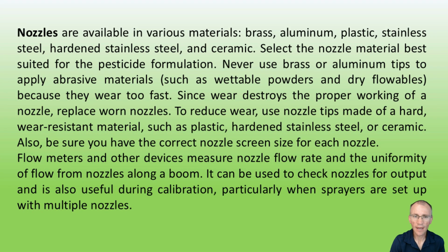Now there's going to be a lot of choices with nozzles. Nozzles are available in various materials: brass, aluminum, plastic, stainless steel, hardened stainless steel, and ceramic. Select the nozzle material best suited for the pesticide formulation. Never use brass or aluminum tips to apply abrasive materials such as wettable powders and dry flowables because they wear too fast.